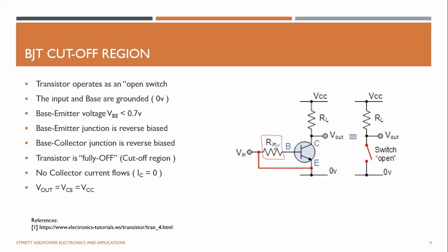Any design engineer will select the Rin value based upon the transistor datasheet, as well as whatever your controller supply voltage comes to this Vin. Those are the two parameters you have to consider. And for this, your load is pretty much a pre-given value. So you keep the load here, and you can take the output voltage from here.